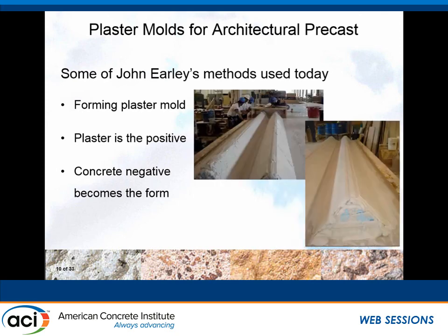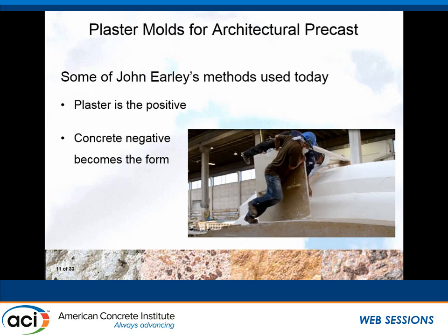And here's the screed, and they run that screed over these to come up with a very smooth shaped form. That very smooth shaped form will be tooled and added with more plaster and cleaned up. Here's a bigger piece. You can see how that screed is run along to create this positive image of what the concrete panel will eventually be.